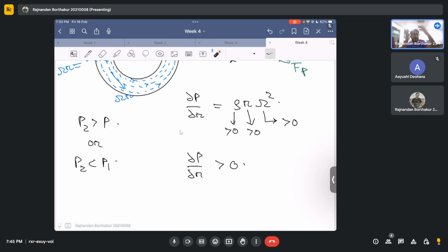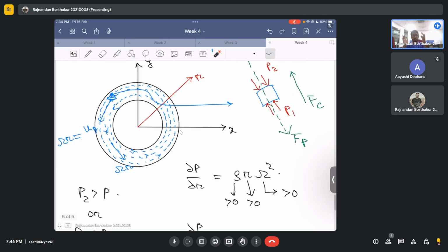Okay, and this pressure gradient is actually what is driving the flow, and what is turning the flow around. And since, as we know, the momentum equation is just the balance between the forces, since the flow needs to maintain its trajectory in the theta direction, this force, which was basically due to the pressure gradient, should be balanced by the centrifugal force. That is essentially the dynamics of a circular motion, the dynamics of the rigid body motion, what we essentially learned in fluid mechanics course.